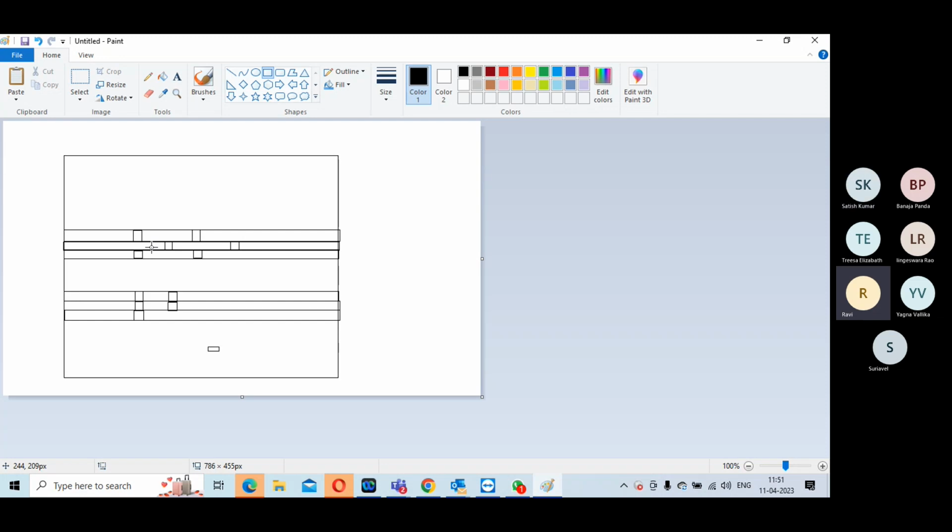If 50 micron is the requirement, and I place a standard cell over here, the cell sitting in the middle is the farthest from each tap. That means this particular pitch has to be 100. Do we understand?